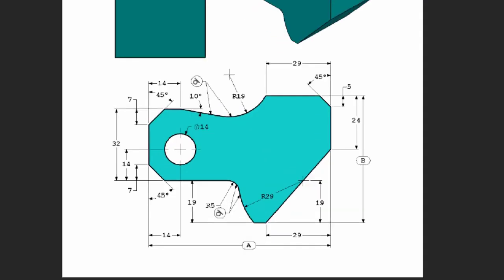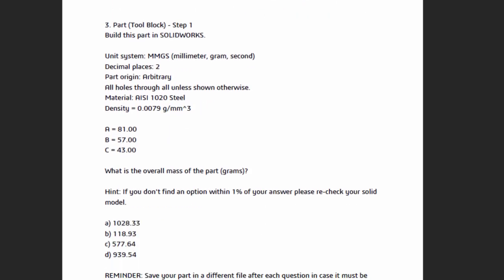Number two is the chamfers. There are 3 chamfer dimensions that are provided. You can do the chamfers in the original sketch, but a key to success with these exams is keeping your parts organized and your sketches simple. I am going to exclude the chamfer dimensions from my sketch in order to save some time, but to also simplify my sketch.